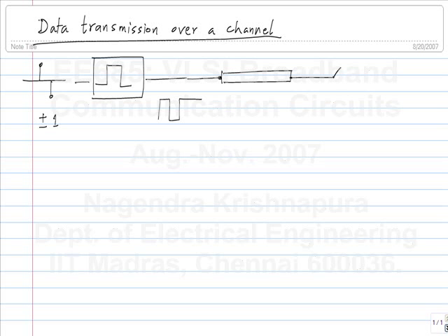At the other end, we sample at a rate equal to Ts, which is the symbol period at the input, and we get some discrete time output. We also saw that we can characterize this whole channel conveniently by looking at the response to a single one, that is, a digital impulse.